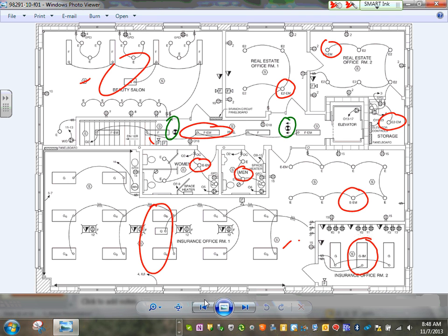You have to have an emergency light. You see that fixture right there? That will be your emergency light, because upon the loss of power, that light will go on and light the path. That's your egress path. So you guys will move in here, you can see the light is here, it directs you all the way out. So you have to design the egress path.